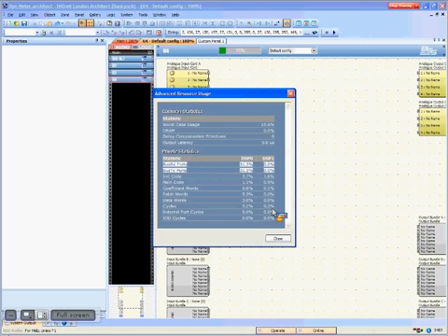Because you think about it, a Blue 80 has potentially 32 CobraNet signals and potentially 16 analog signals for a whopping total of 48. So yes, it should have been called the Blue 48, but we won't argue about that right now. So you can't overload the 128 input channels.